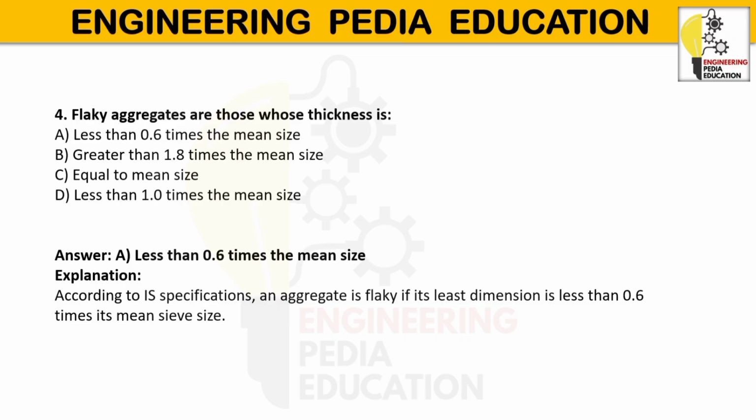What are the characteristics? Thin and flat in shape, provides poor interlocking compared to cubical aggregate, has larger surface area requiring more binder or cement paste. What are the effects on concrete and pavement? Reduced workability, may decrease strength and durability, can break easily under load.